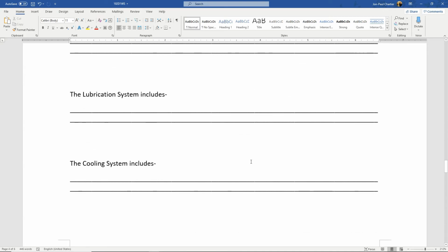The lubrication system on the car. This is important for you guys because what you're touching right now is lube tags, oil, drain plug, oil filter, oil pump, and that's it. There will be a gauge or a dummy light in the vehicle because if the oil pressure gets low, what happens when we have 2 pieces of metal that are very hot rubbing on each other? They'll melt together. So this is important. This is like the most vital thing, this lubrication system, but it's really simple.